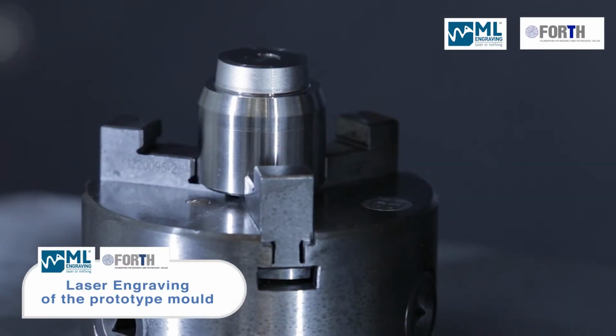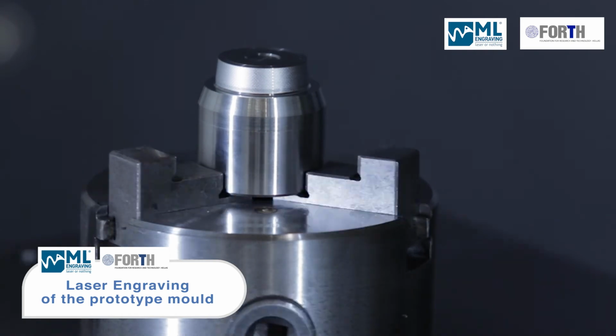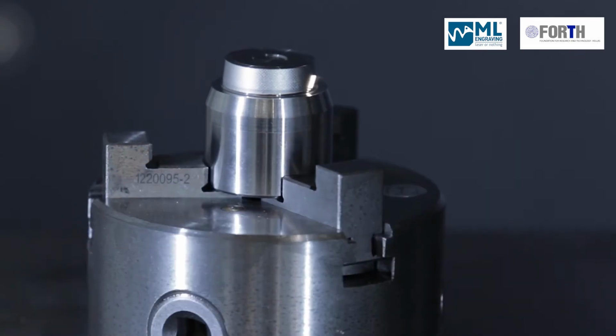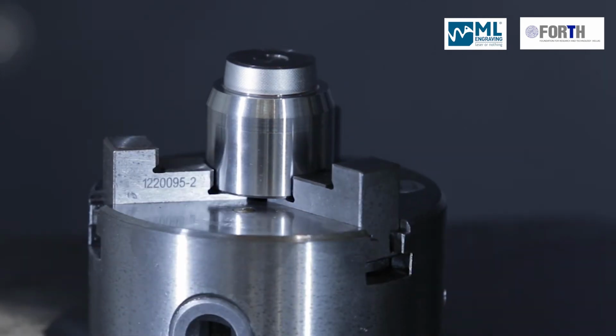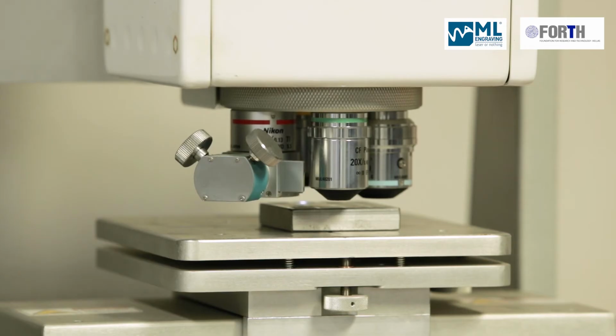Following the DDDR definition, the prototype mold is laser engraved to create the textured surface. The laser process creates micro-dimples that will permit the seal to be manufactured directly with the defined surface microstructure. Optical measurements with Filmetrics are made to verify the laser engraving and check that the microtexture is adequate with the DDDR texture selected.